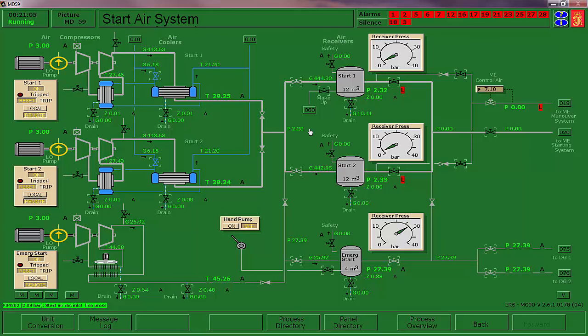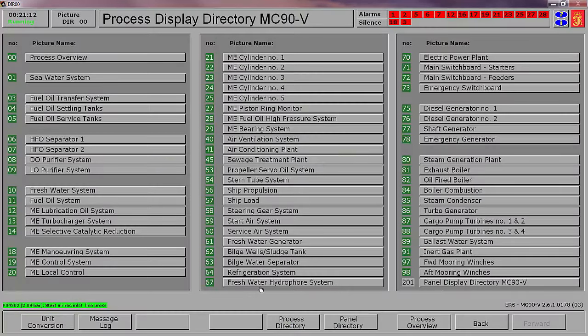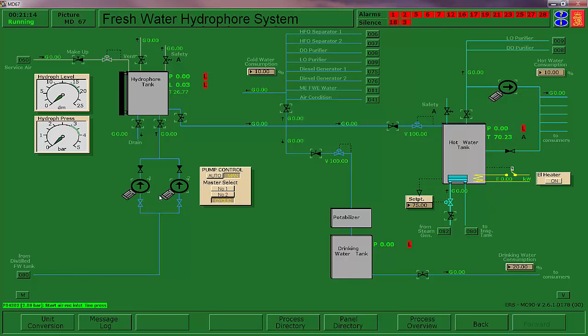Okay, so we've got that filling. All right, let's go ahead and look at our potable water system. We'll go ahead and open the line from the pumps to fill it. Its outlet to the system. This valve goes up to the engine room. This is to the house.